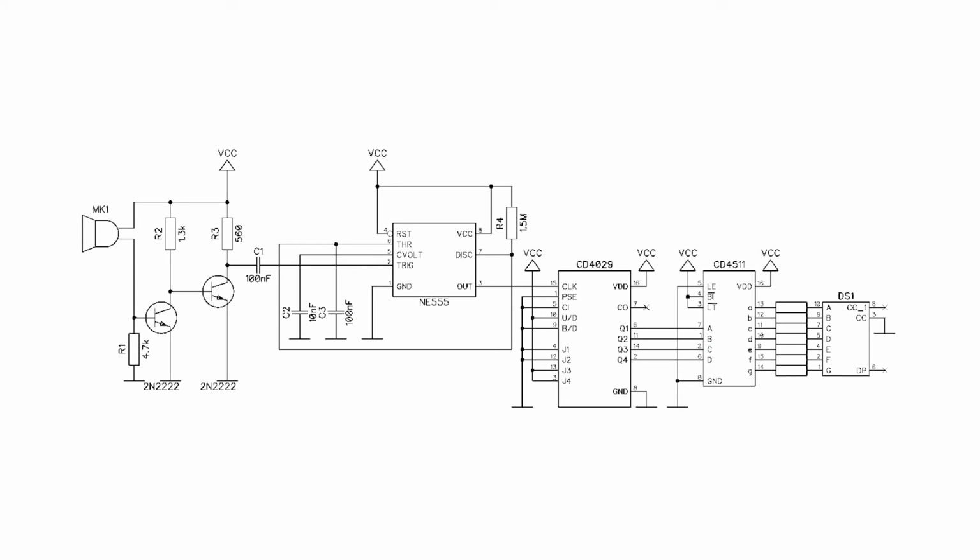Electret microphones are for us like capacitors, where one of the claddings is an acoustic membrane. When it begins to vibrate, stimulated by sound waves, the gap between them changes and thus their capacity changes. In standby, the microphone has full power supply voltage. When it starts to work, the variable capacity will force the current flow through the microphone to R1. This will start switching on the first transistor, which amplifies the signal from the microphone. The second transistor analogously amplifies the signal even more.